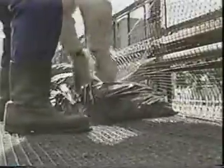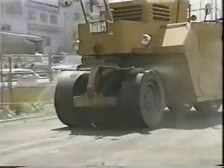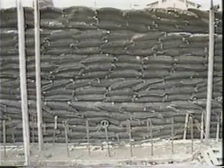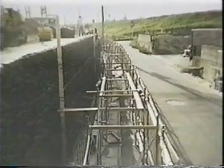In Japan, a staged method of construction is often used to overcome differential settlement. Flexible, gravel-filled geosynthetic bags are placed at the shoulder of each soil layer, wrapped with a flexible geogrid, and secured with staples. Soil is placed up to the face, and compacted. After the settlement of the supporting ground and the fill, a full-height panel facing is cast in place.